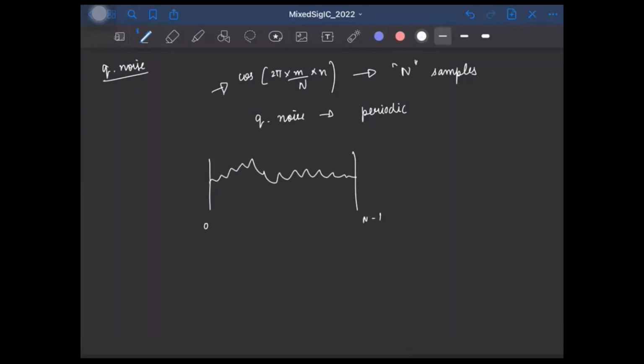What the DFT assumes is a periodic repetition of this same waveform on either side. So there will be no jumps when you extend this on either side, and no problem of FFT leakage if we ensure that the signal is falling on a bin.